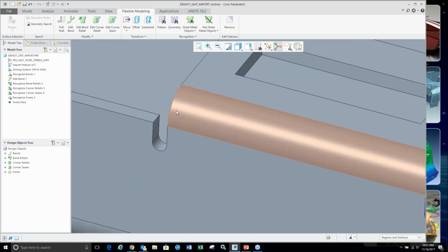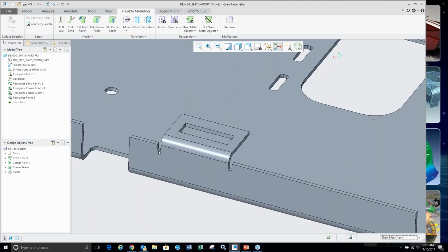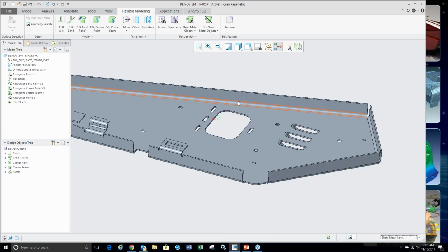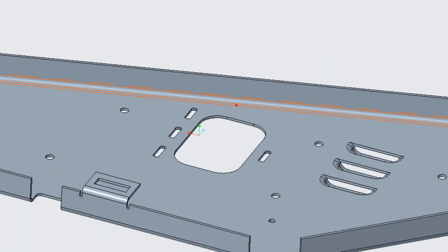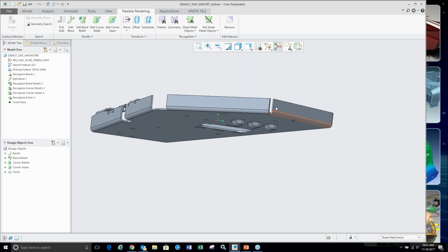So now if I go to those identified objects, right, I do have a filter for Sheetmetal items. It tells me, see, the width and the depth, that's a bend relief. It tells me information about that bend. This is very important, right? When I go and, you're essentially looking at, you get the information tools. It'll say what type of corner relief it is.